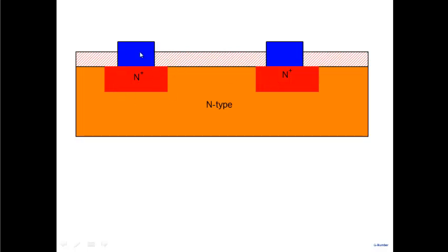This whole thing acts as a very good contact with very little drop here. And now, where do all the drops occur? They occur across the N-type semiconductor. So that's why everywhere that you will see in semiconductors, wherever you want to form a very good contact, you will find under the contact, there's very high doping. If you want a P-type contact, you would have made P+. If you want an N-type contact, you make N+. And that's how you make a contact which is very good. So very high doping is the trick.